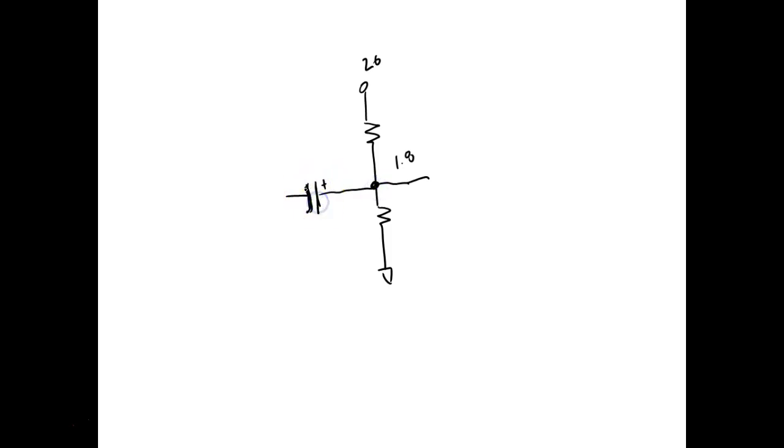Okay. And it's allowing us to bring a DC voltage in right here. We'll talk about how to put these polarized capacitors in there. And what it's letting us do is bring an AC voltage in over here. So one of the main things we talk about, what does a capacitor do for us? It blocks DC and passes AC. Now the amount of AC it passes, you'll learn later on, would be dependent on frequencies. But we're going to choose a capacitor that's big enough so the frequency doesn't matter.